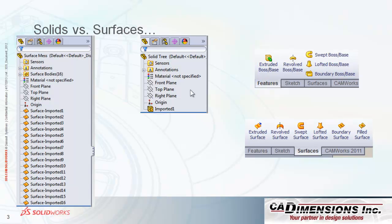You will see it many times with garbage in, garbage out, or like I like to say, good stuff in, good stuff out. If you bring in a model that is not in the best shape, you might see that there are some gaps and some faulty faces on that model, and that can cause SolidWorks to create surfaces instead of an imported solid. That is simply because SolidWorks needs the model to be watertight. I'm going to show that in a second.